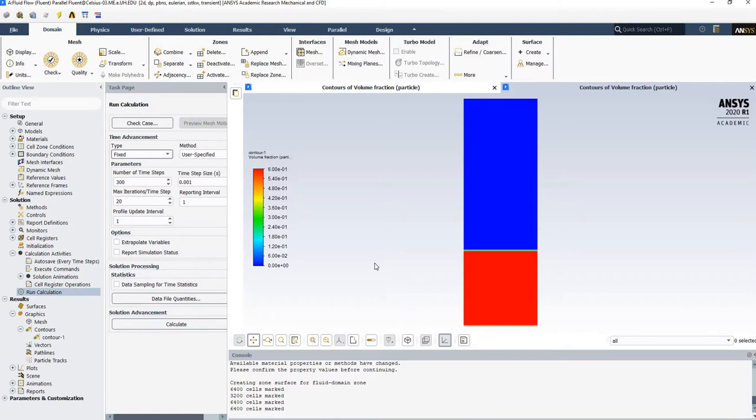I think those two are mesh and the velocity that directly relates to the Reynolds number, I think, as well as the time step size. Okay, so this has a proportional and inversely proportional relationship. So the way it works is if you have a higher velocity, Courant number will go high, and you don't want that because that would cause divergence.